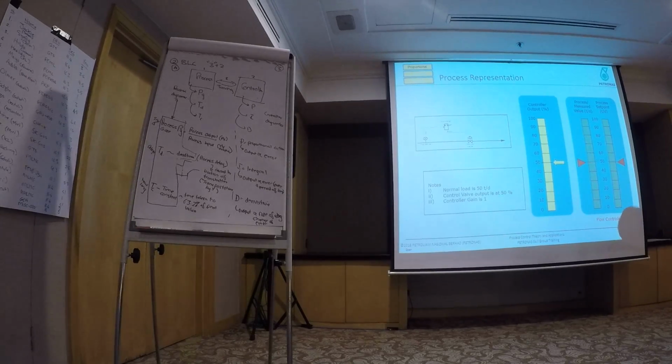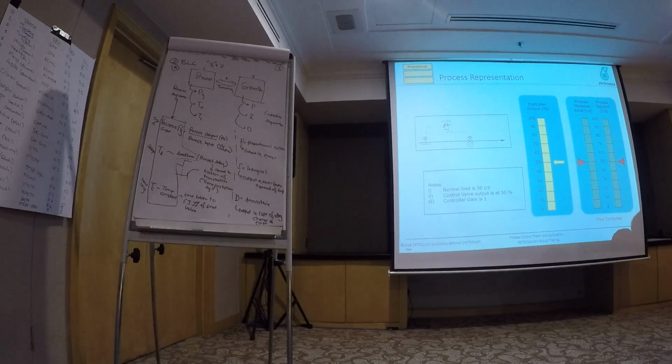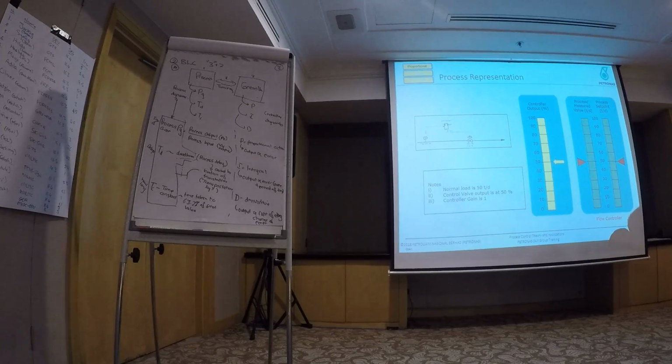So it's either minutes per repeat or seconds per repeat, but in some, and we're not talking about DCS-based, but standalone controllers. In standalone controllers, you'll get the other version, which is repeats per minute or repeats per second. Okay? But these are not common.